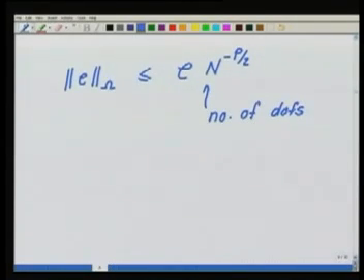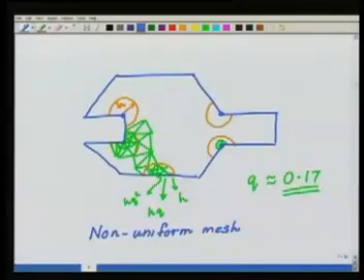Okay. This is now optimal for the H version of the finite element method. Now I can use a combination of H and P. That is, I start raising the P. So here, if you see this, in the vicinity of the corner the solution is singular.